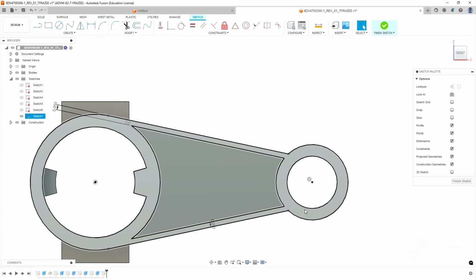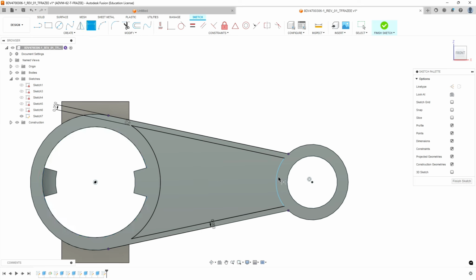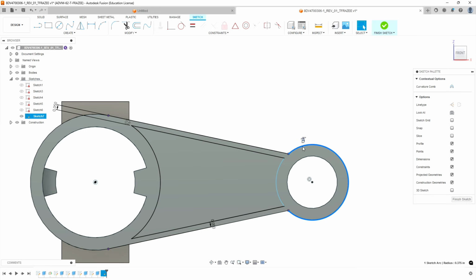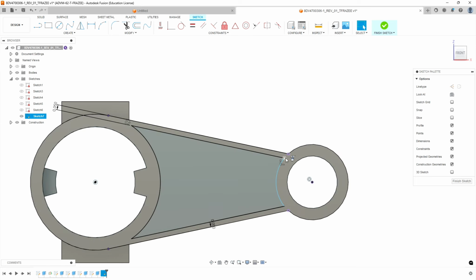Looks like I lost my reference, so let's just go ahead and dimension that guy. Oh, we got a big piece of circle left. So we've lost a reference for that corner that I thought was so great. Let's just go ahead and put a dimension in there. And that works. It's a 375 thousandths radius, which is half of what the diameter was. Alright, everything should look constrained like this before we start.